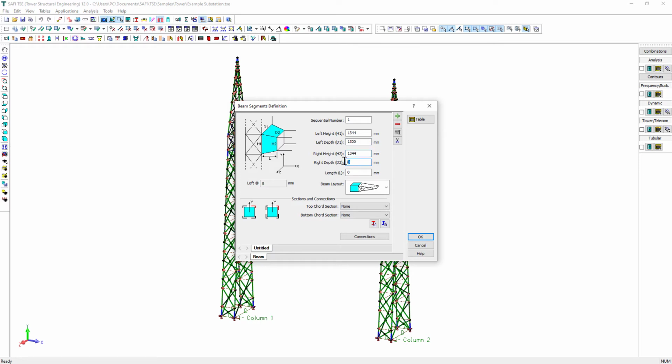When a beam is defined with multiple segments, the length of each segment is of course important. However, if one segment is used to define the entire beam, and the beam is not a cantilever, the length of the segment may be set to any non-zero value. The segment will be stretched to the entire length of the beam.